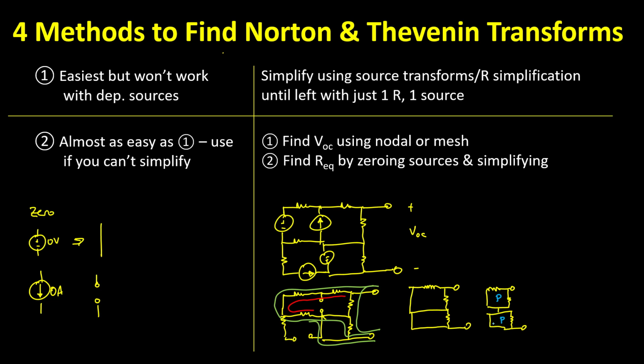It's a resistor in parallel with a short. And so their combination, a resistor in parallel with a short, is just a short. So now we can draw this more simply. If we call this R1, R2, and R3, we can draw it as just R1 in parallel with R2, and then R3 goes away because it's been shorted out. And that is our REQ.